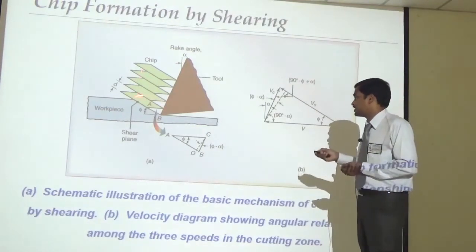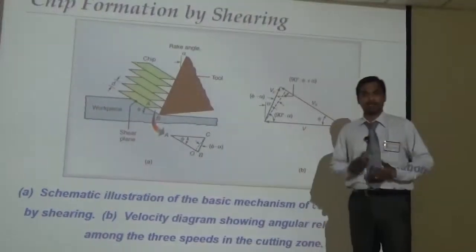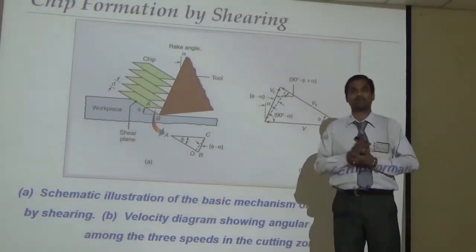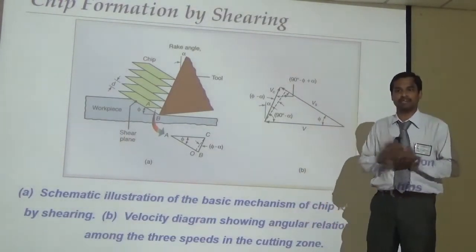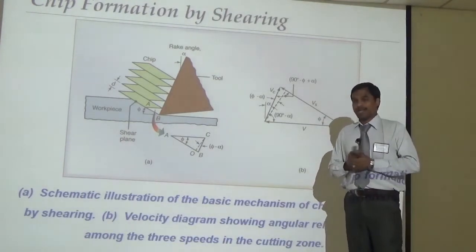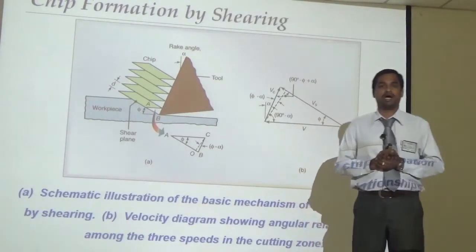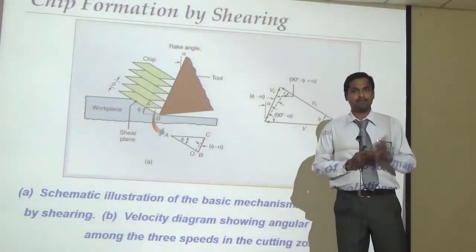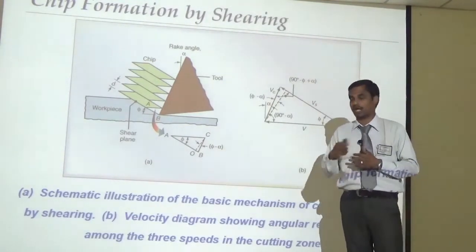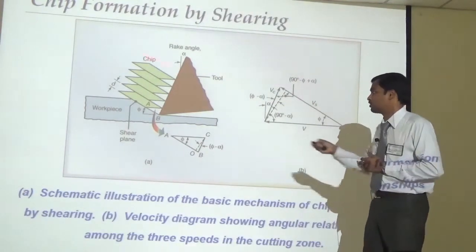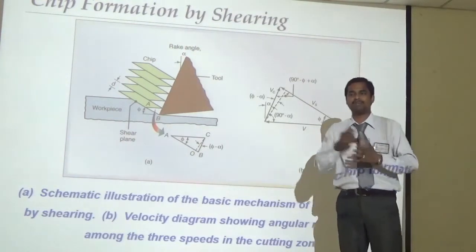Before that, we should know about the simplicity in material removal process. In the material removal process, the analysis of cutting forces is important since this contributes more towards performance. Normally, common processes like turning or milling involve 3-dimensional cutting. That means oblique cutting. The obliquity is the angle between the cutting tool edge and the cutting tool velocity. Cutting tool is moved in this direction, that's cutting tool velocity, and cutting tool edge direction. So this obliquity